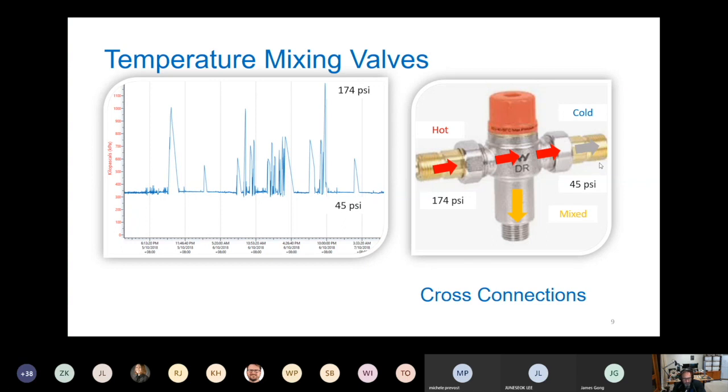If the system can't get back into the street mains, then the cold water pressure, like it did in this dwelling, will also go to whatever the pressure is driven from the hot water heater. So we can now have double our water pressure above the standard within our systems. Or we can lead to other problems, like unintentional heating of cold water, increasing the rate of microbial growth.